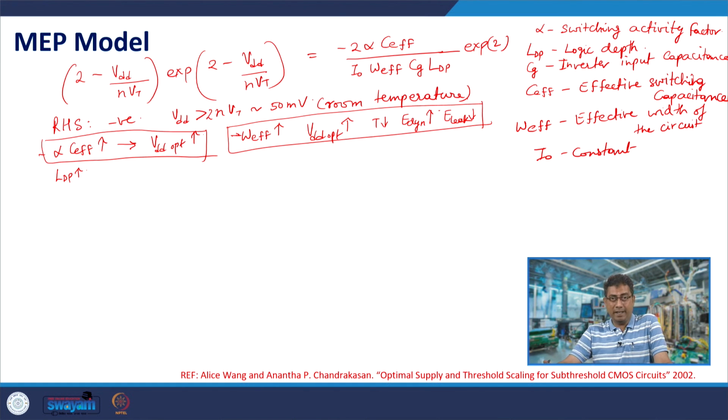So, therefore, it is leakage energy which you are increasing per cycle within a data path. If you look at the energy within a data path, you will find that the leakage energy increases. Now, to reduce leakage energy, you would have to increase the VDD and thereby reduce the time period. You reduce the leakage energy, but you increase the dynamic energy. So, you get a new optimum VDD which is larger than the earlier optimum VDD; it increases.